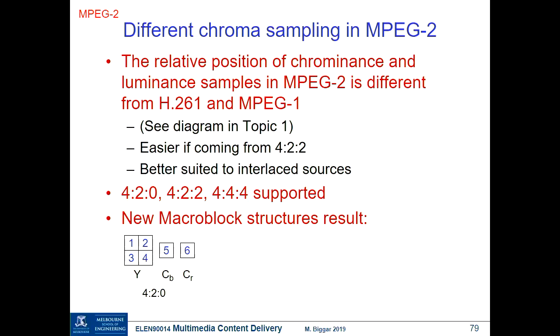So what this dot point is, and sorry, I shouldn't have bothered with it, is that with MPEG-2, that physical location of the chrominance samples was not necessarily well suited to this interlacing, as you might expect, because some pixels come from one field, some pixels come from another field, and so they allowed for different definitions. But I don't want to say anything more about that for now.